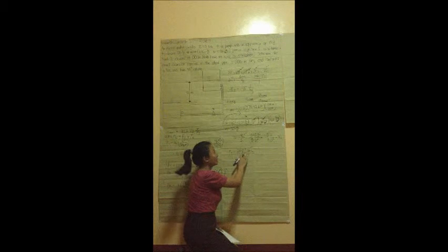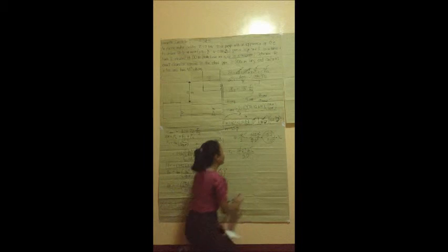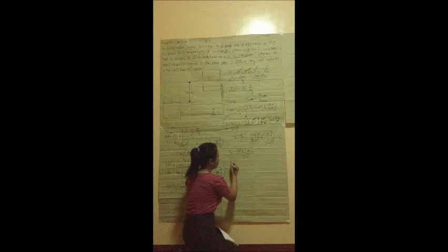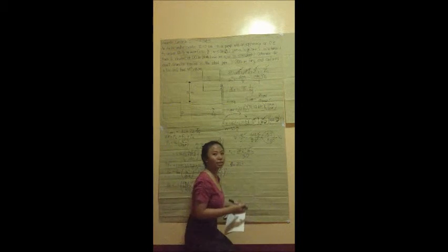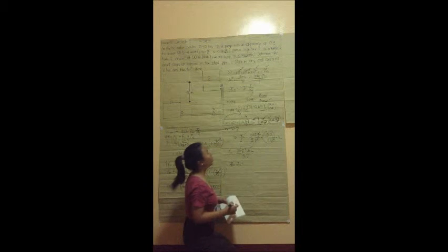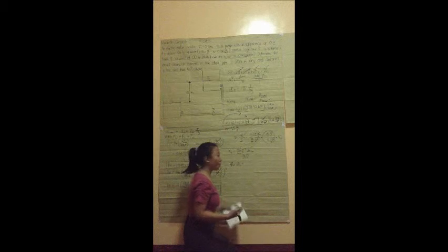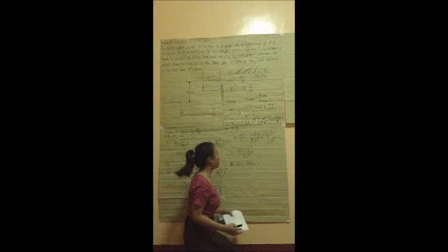This is the value of the velocity that we are going to substitute here later. So F has the value, let's first get change in L. So change in L is the sum of all the lengths of the pipe, including the fittings and the valves. So we have a given length for the pipe, which is 200 meters. And let's add the length of the fittings and the valves. So in the problem, we have a T and the two 45-degree elbows.